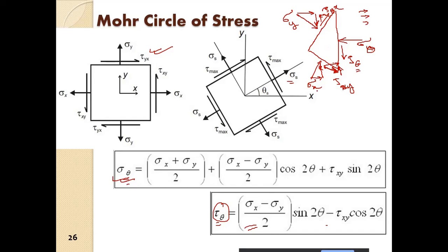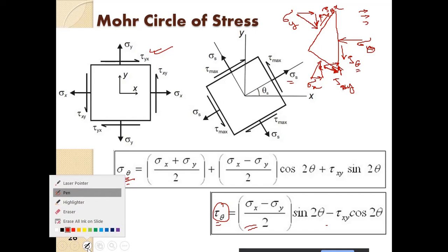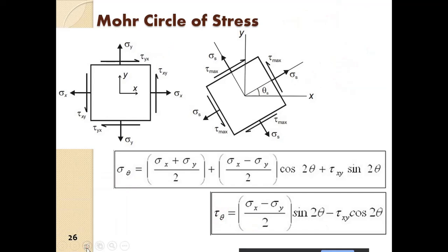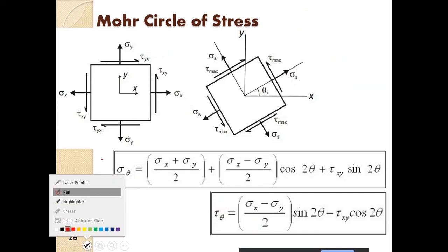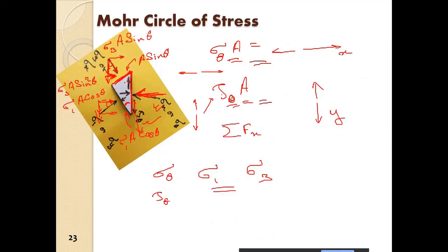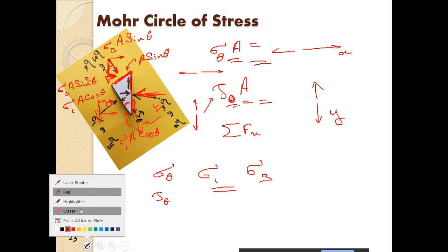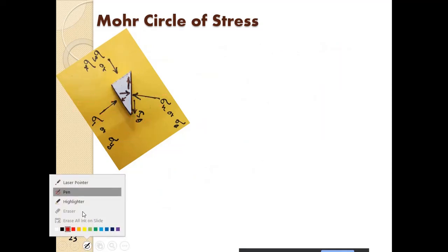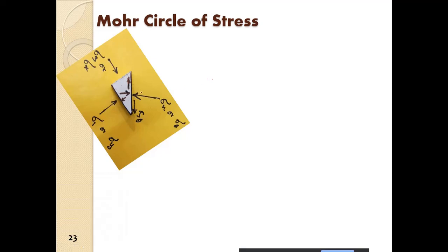So the thing is that you are actually panicking. It is not like that. You solve one condition at a time. Just like here, what I have done is, I have rotated the element. So this is the normal stress into the area. I have to convert this into force. So normal stress into area, that is the force.